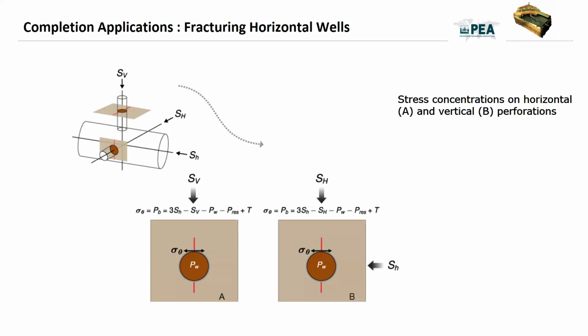Most horizontal wells are stimulated from cased hole completion. You know that. So this completion option provides greater control. If you stimulate in a cased hole or in an open hole, it is not the same, as you know. So this completion provides greater control of where fluids are injected, and to some extent fracture geometry, by selecting the location and orientation of your perforations.